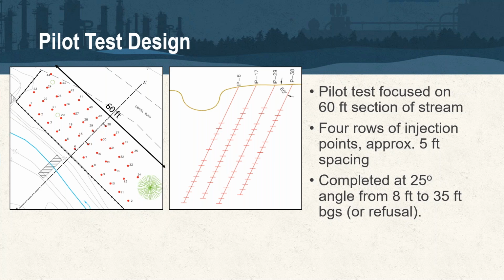And the injection volumes are going to vary depending on the geology. So if you're working in a clay or a silt and you're on that 5 foot spacing, you might be working in 10, 12, maybe 15 gallons per interval. And those intervals are going to be spaced vertically, say 1.5 to 2 feet vertically. And as that injection spacing increases, assuming you have a site where groundwater is deeper, if you're in that 10-foot spacing, maybe you're in the 40, 50, 60 gallon range of slurry. And so those are injected at relatively high flow rates.